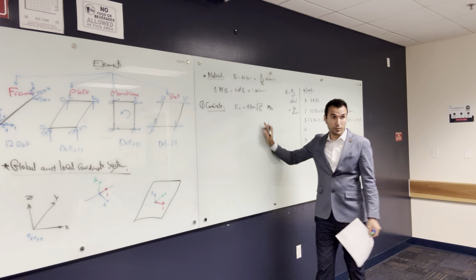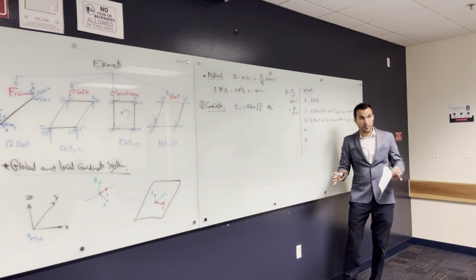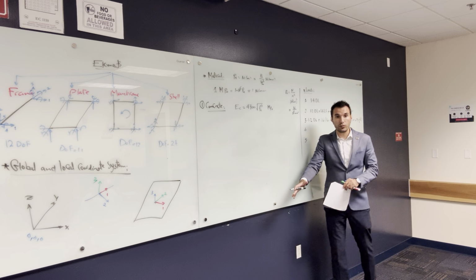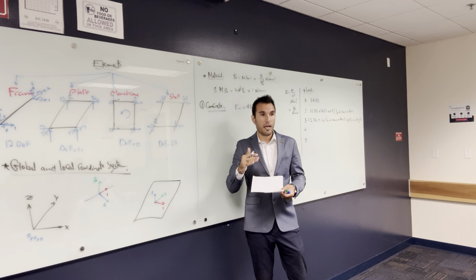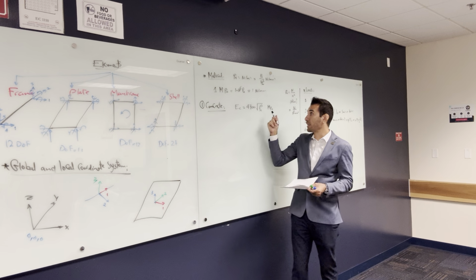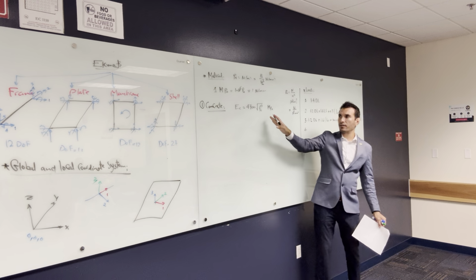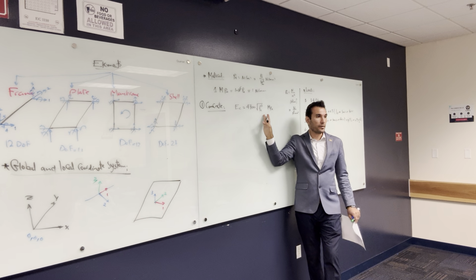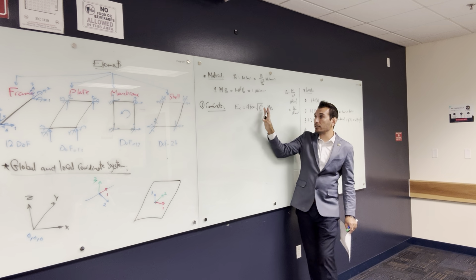Do you know what the characteristic strength of the concrete is? You take some samples from the concrete that you are using on the site, and you do the compressive test, and you take the average, and the average is going to give you, after 28 days, this value. Usually, for each project, you have the FC.